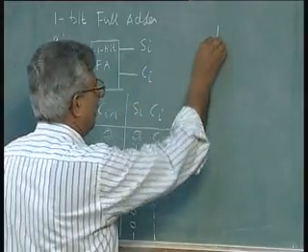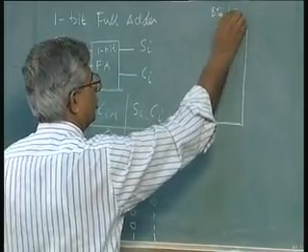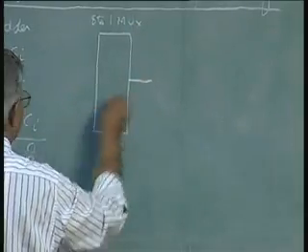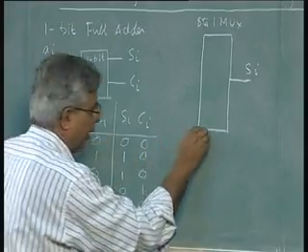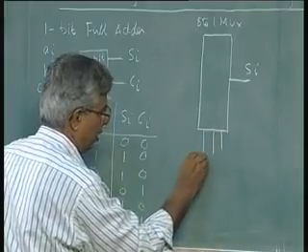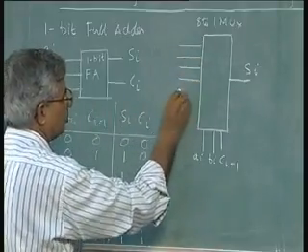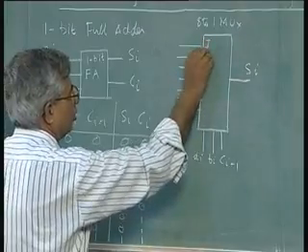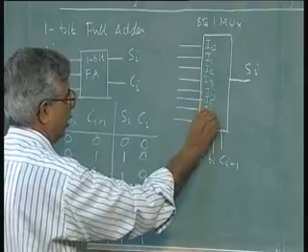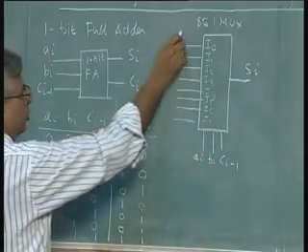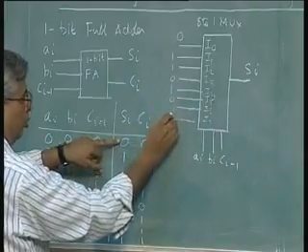So I am going to use a multiplexer with 8 inputs and 1 output, an 8 to 1 mux, and the output F is nothing but Si. The inputs are 0, 0, 0, the output is 0, like that. So I need to connect my Ai, Bi, Ci minus 1 to my selectors, and connect to my 8 inputs I0, I1, I2, I3, I4, I5, I6, I7 these values as they are: 0, 1, 1, 0, 1, 0, 0, 1.